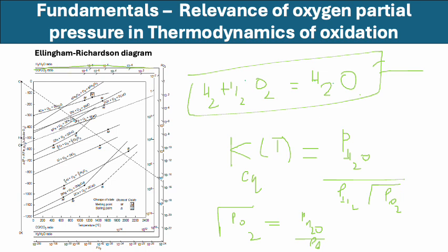Now when you are talking about using this ratio, you need to draw a line from this point, the point H. So what does it mean if I draw a line from here, if you are talking about an oxide, for example copper, at let's say 700 degrees Celsius itself, let's take an example of copper at 600.